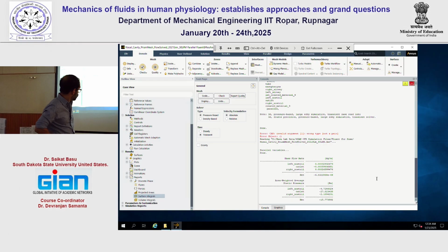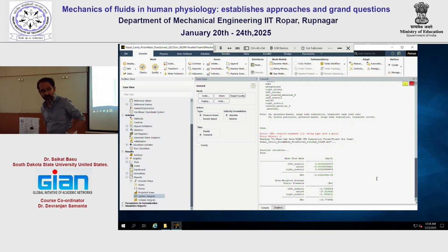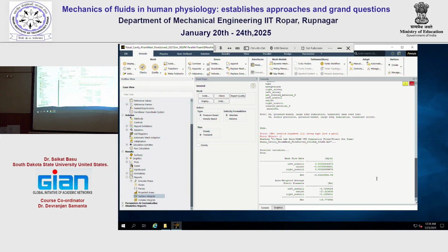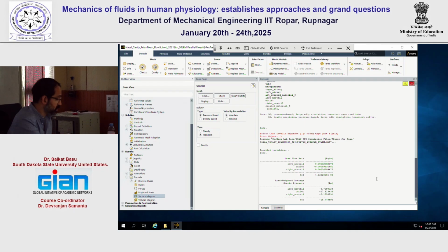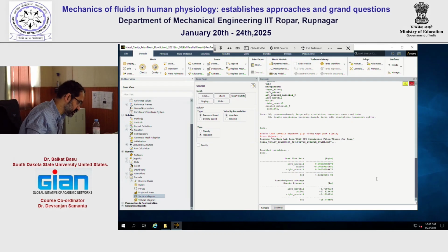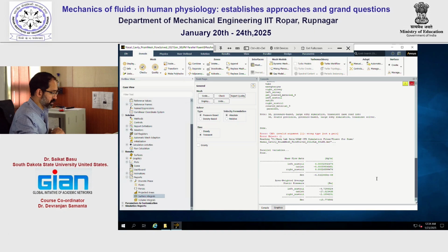Now, we also have to report the delta P. To report the delta P, I take the absolute pressure of the outlet, figure out the mean of these other two, and then subtract that from here. Let me go to your printed pages, and there is an example of this, but it's a different simulation, the one that I have included in the printed pages.